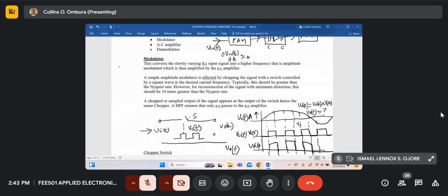Then you multiply in time the input frequency, which is 1 kilohertz, times 10. So you'll add and subtract, because now it would be a DSB signal. So you'll get a spectrum at 11 kilohertz and 9 kilohertz. You repeat the same with the other harmonics of 30 kilohertz, then 50 kilohertz, 70 kilohertz, 90 kilohertz, etc. Of course, it will be diminishing according to the sinc function.